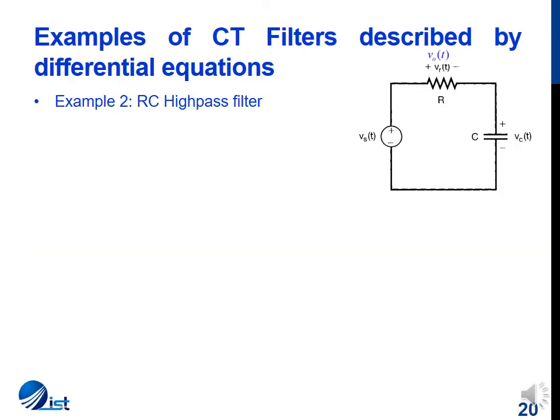Let us explore the series connected RC circuit of the previous example and now take the voltage across the resistor, V0. In the previous example, we saw that the circuit gave us a rough approximation of a low-pass filter. Over here, we'll see that when we take the voltage across the resistor, the circuit will behave as a high-pass filter. So once I apply KVL, this is the equation I get, and assuming that the frequency response of the circuit is given by G(jω), this is the frequency response of the circuit. The use of H or G does not make any difference.